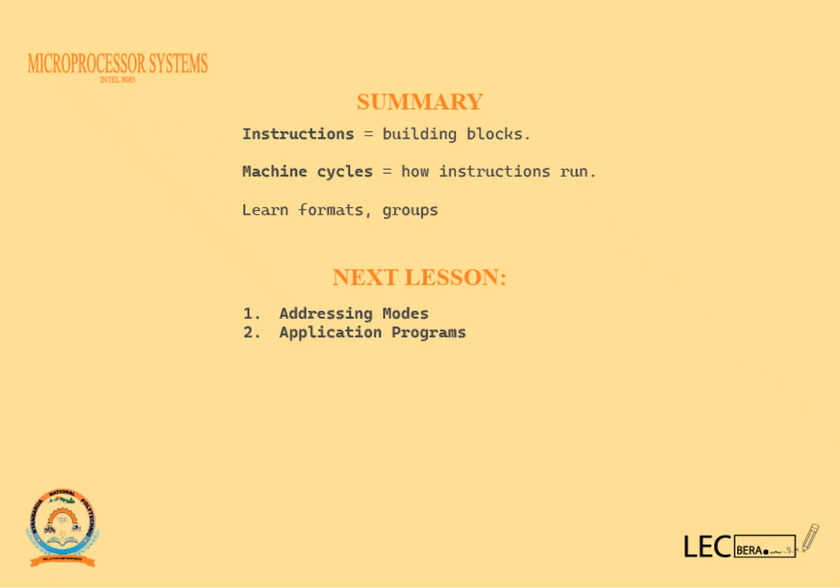Clock signals. A clock signal contains a rising edge and a falling edge. To measure one period of the clock signal, we measure from one falling edge to the next falling edge, and that period is the same as one T-state.